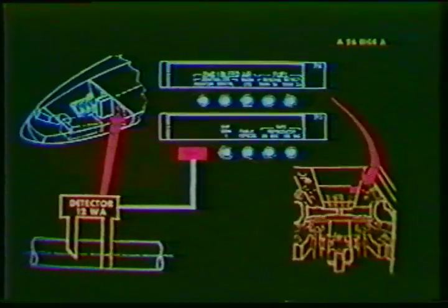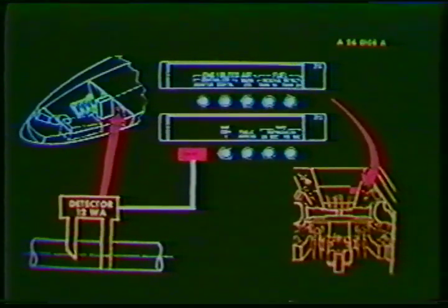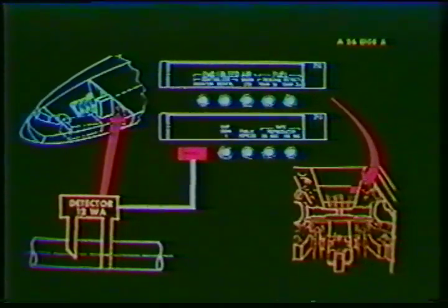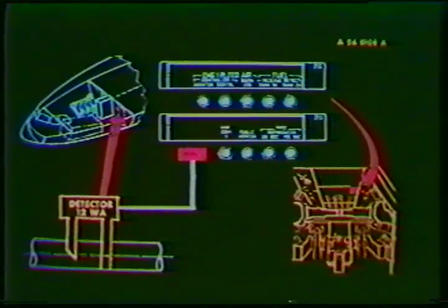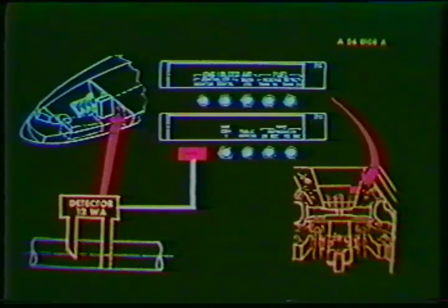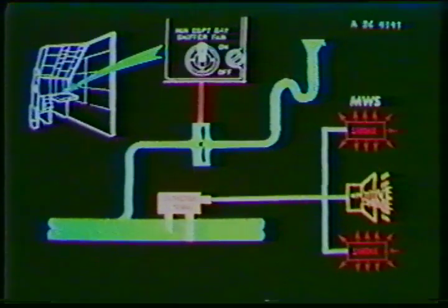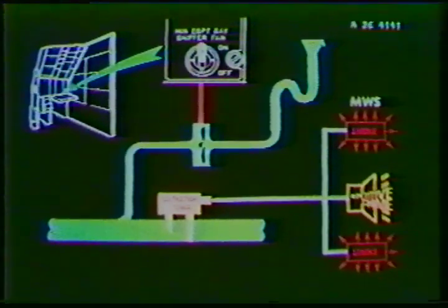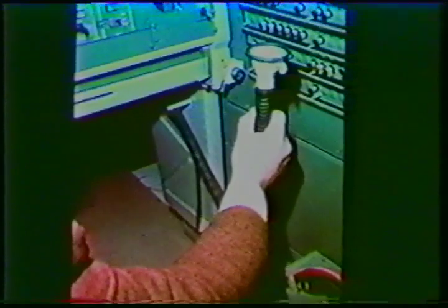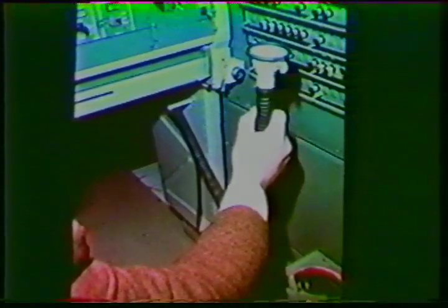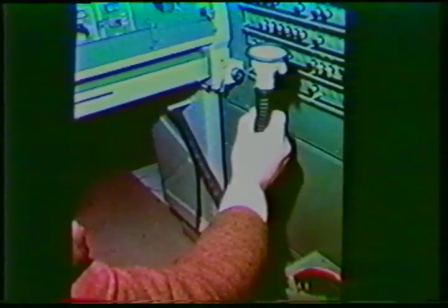In the avionic compartment, a smoke detector monitors the airflow coming from the fireproof compartment called the minimum equipment bay. This detector is associated with a smoke warning light located on the overhead panel. When this detection causes a smoke warning, it can be quickly confirmed by a smoke sniffing provision. The sniffer itself consists of a flexible hose below the right side of the second officer panel. The sniffer fan switch is at the lower right side of the second officer panel.